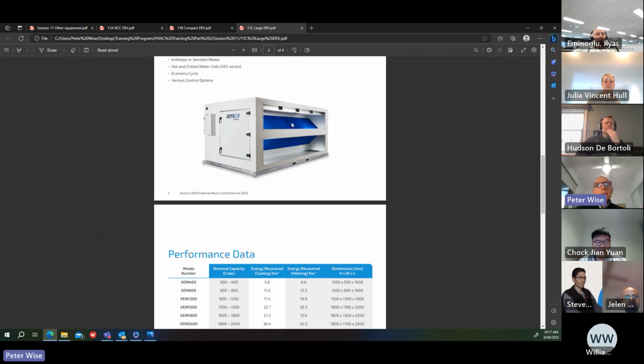And so you've got air coming in and two air streams running parallel to each other, the fresh air and the return air, and they're traveling through different plates. Now, I don't know how they achieve that actually, but they separate the air streams, but the heat exchanges through the plate element, which in this case, that blue material, I think is a polypropylene material.